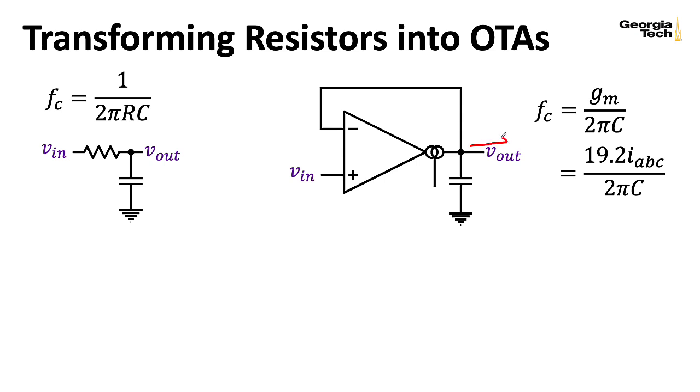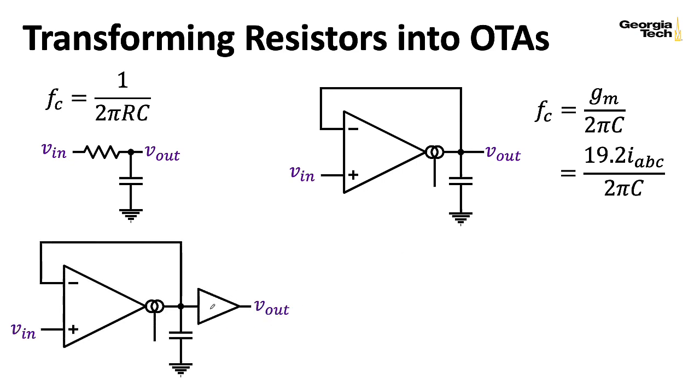Of course, we might be feeding something that doesn't have an infinite input impedance, so something we might do here is to place a buffer at the output. And this triangle is basically an ideal voltage buffer. This is the sort of thing you can build with an op-amp by putting the input into the positive terminal and taking the negative terminal and connecting that to the output. Or you could use something like an emitter follower if you're using a BJT, or a source follower if you're using a JFET. Here we're just assuming it's an ideal voltage buffer.